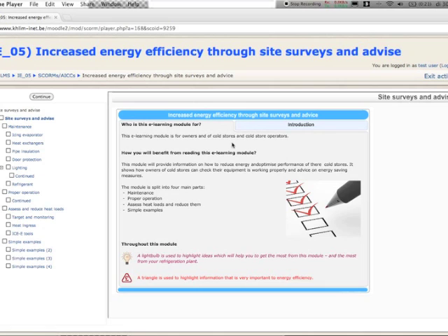Here, the maintenance proposed is something very basic, what everybody can do. Although, if you have a very technical background, it's okay. If you don't have one, it's no problem. This is just for someone who owns a cold store, who walks in and sees a problem. For instance, icing of the evaporator. If you see ice on the evaporator, it's not a good thing. You have to check into it. And that's how this module is created.